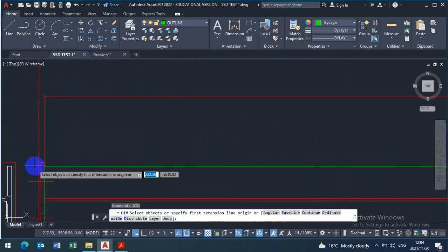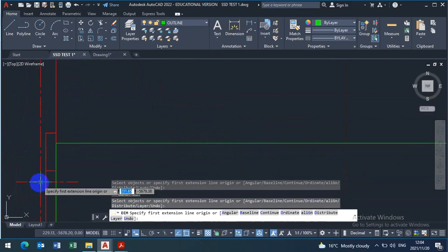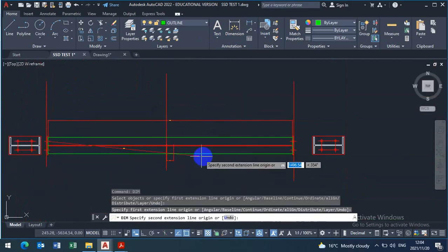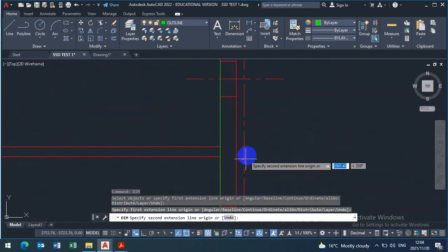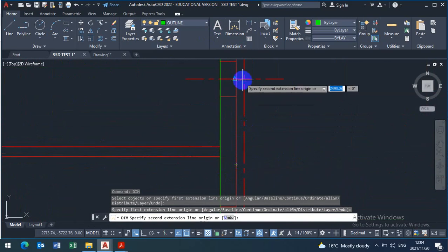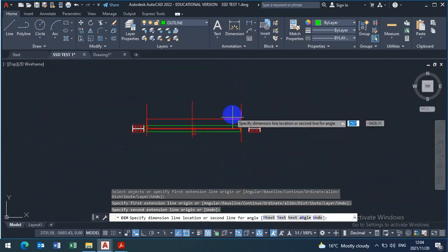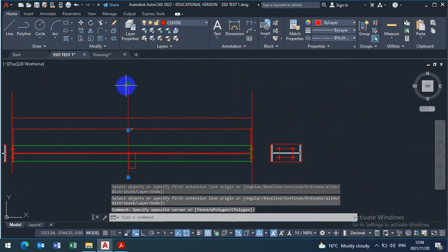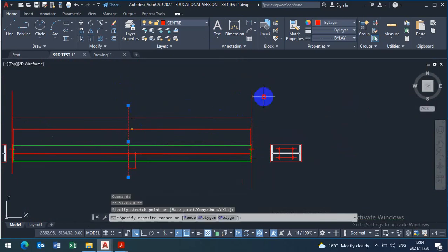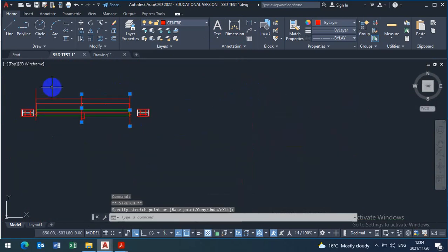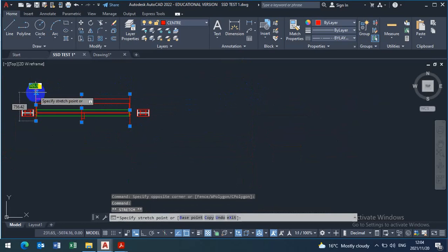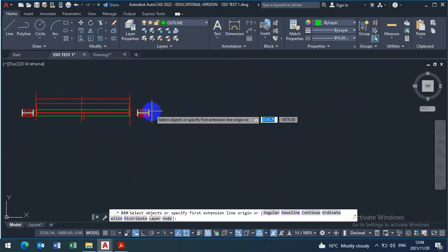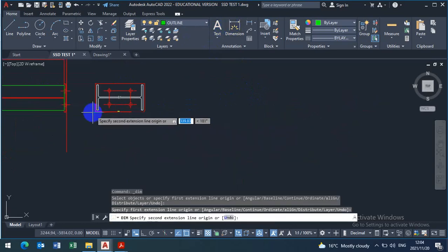Beam 1 was going into the column web, and the center was from here to there. You need to leave the column centers. Okay, and then you show the distance here. Try to make them neat and short. And then we put the plate size.